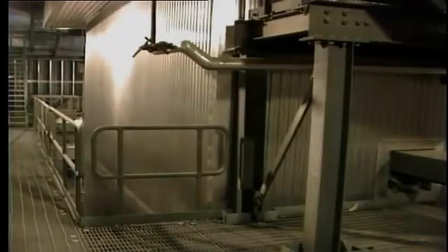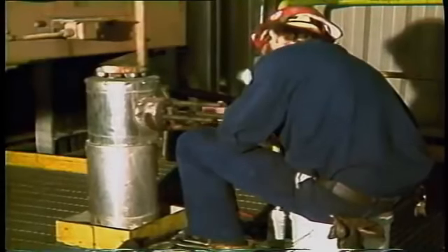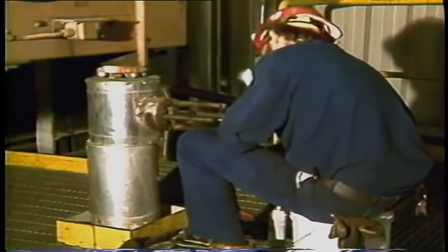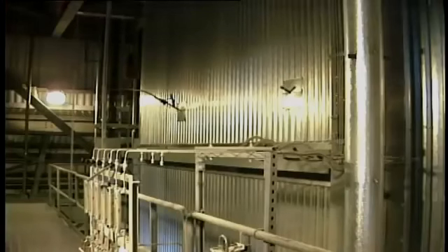The insulation is held in place by the boiler casing, which is made of relatively thin sheet metal that has no structural purpose in supporting the boiler. In a well-insulated boiler, we can quite comfortably walk in the vicinity of the boiler without feeling excessive heat emitting from the casing. However, where insulation is faulty, we will feel the high temperature in the locale, and the boiler casing may glow red. Access ports are often provided to allow us to look into the furnace at strategic points and also to enter the furnace during maintenance shutdown.